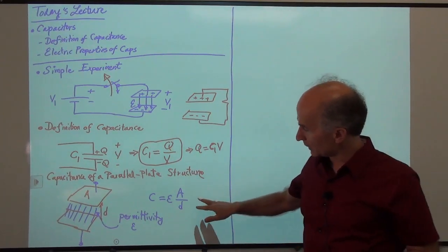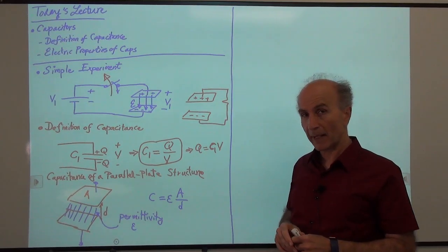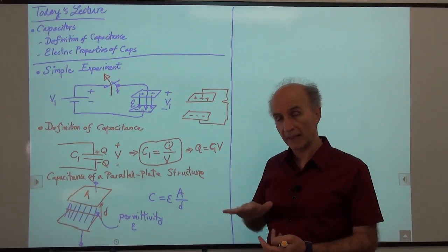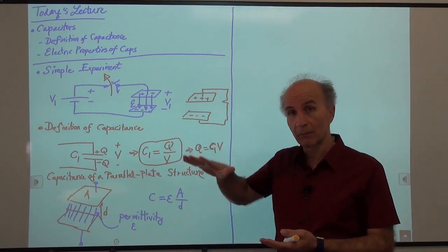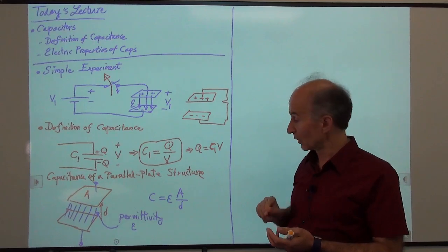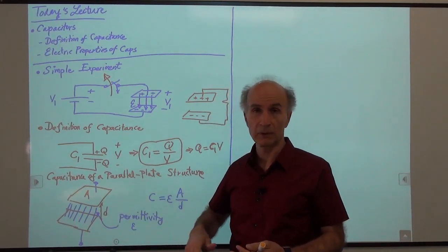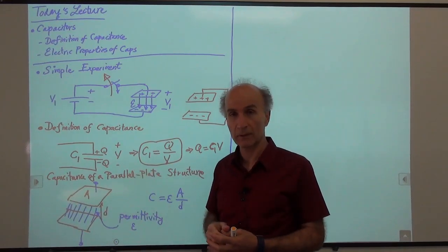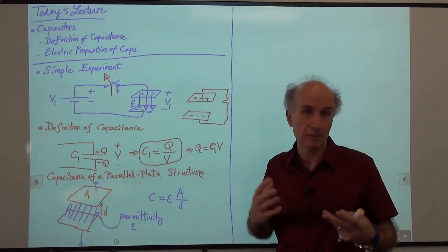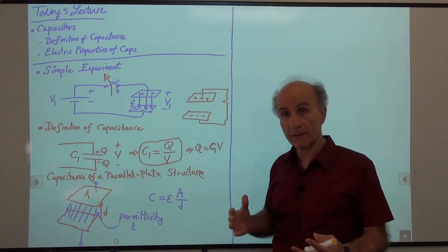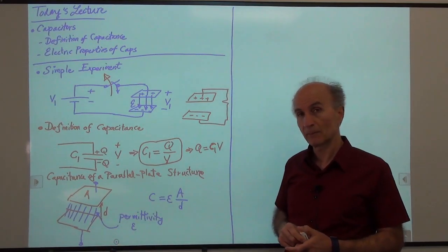This equation tells us all sorts of interesting things. It says that the capacitance between two plates becomes larger as the plates themselves become larger. That's a useful rule to remember if you're trying to build a larger or a smaller capacitor. If we're trying to minimize the capacitance somewhere because it's bothering us, one possibility is to minimize the area of these plates.